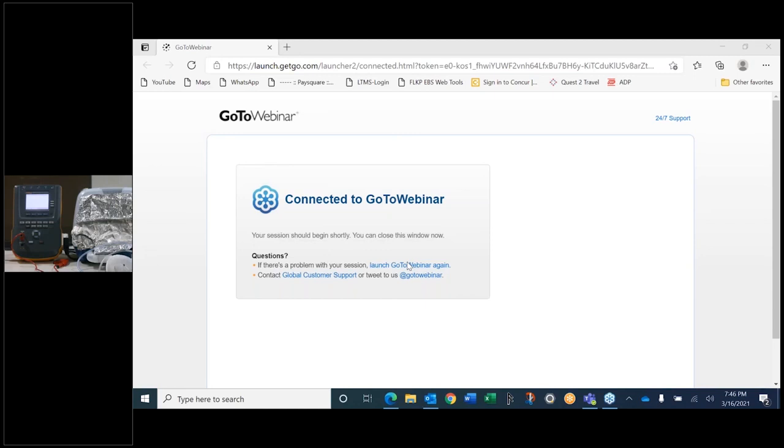And another advantage about the ESA 615 is you can set your flow. You can prefix in 62353 which equipment you are going to do, a ventilator. These are all the programs that have to be run, and the auto sequence can be run automatically. It will guide you how to do the test, and finally the results can be saved and transferred to your computer.